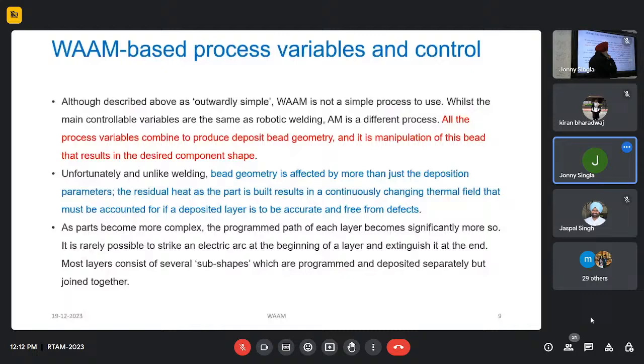And of course, when we say residual heat is to be managed, one major challenge associated here is generation of residual stresses in your component. Residual stresses means when everything is relieved, still there is a certain level of stress in your component that continues to reside within that deposit. And having residual stresses in any component is not a good thing as far as performance of that component is concerned. In what way? Because your component is already in the pre-stress state.